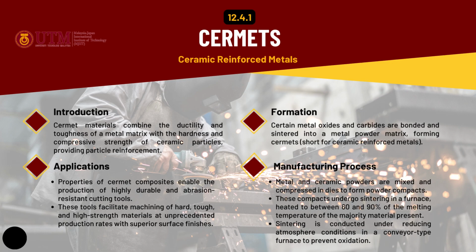For formation, certain metal oxides and carbides are bonded and sintered into a metal powder matrix, forming cermet. For application, properties of cermets enable the production of highly durable and abrasion-resistant cutting tools. These tools facilitate machining of hard, tough, and high-strength materials at unprecedented production rates with superior surface finishes.